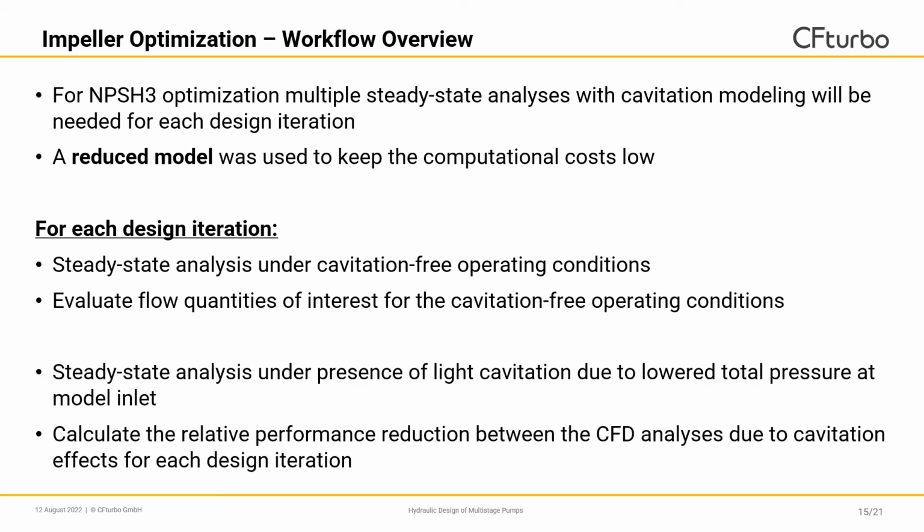Then we performed another steady-state analysis, but this time under the presence of light cavitation due to a lower total pressure at the model inlet. Then we calculated the relative performance reduction between these two CFD analyses for each design iteration.